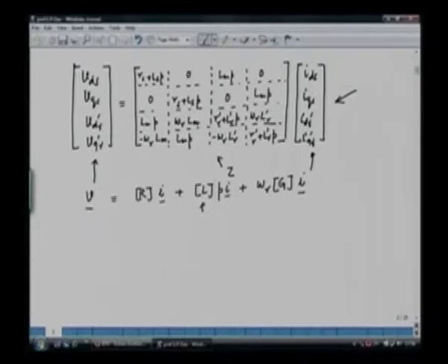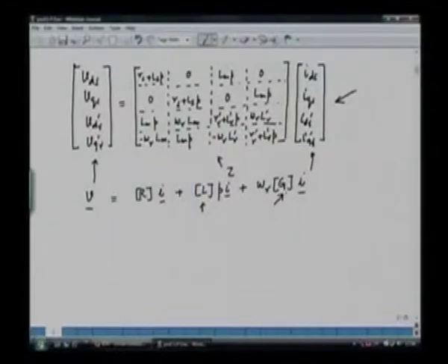So this matrix can be easily evaluated. Those elements which have got derivative terms are clubbed into L matrix, and those elements which have got the speed term are clubbed in the G matrix, as you have already seen in Kron's primitive machine model. And this G matrix can be easily identified.